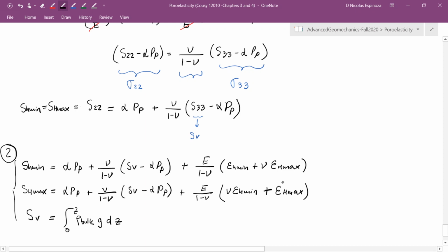This is a drained problem because usually when these tectonic strains are applied, they have enough time to let the pressure in reservoirs or in rock formations dissipate, so there is no undrained loading. There are some cases though in which you do have undrained loading due to tectonic strains. But let's not get into that case right now. Let's consider the drained problem.